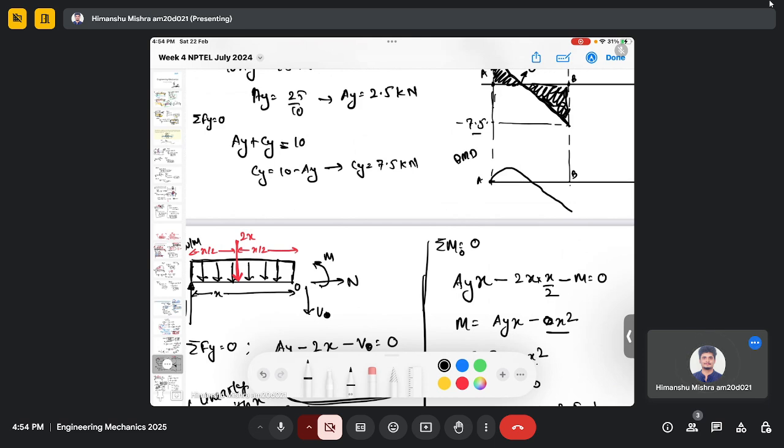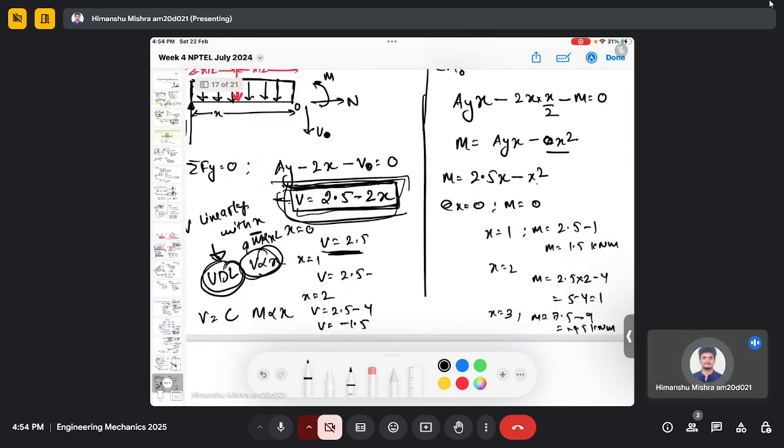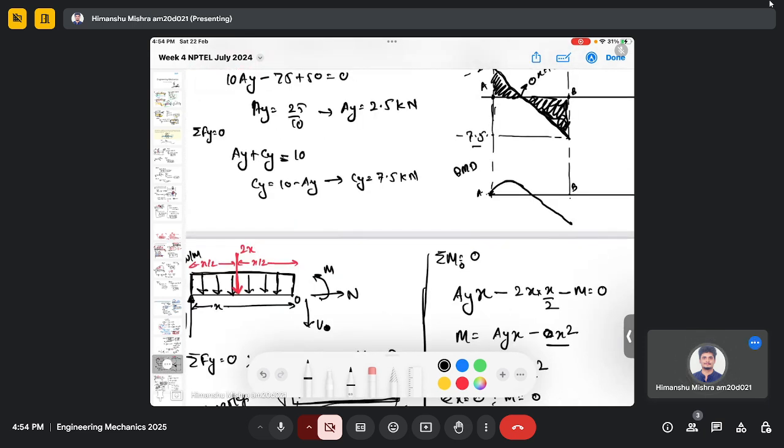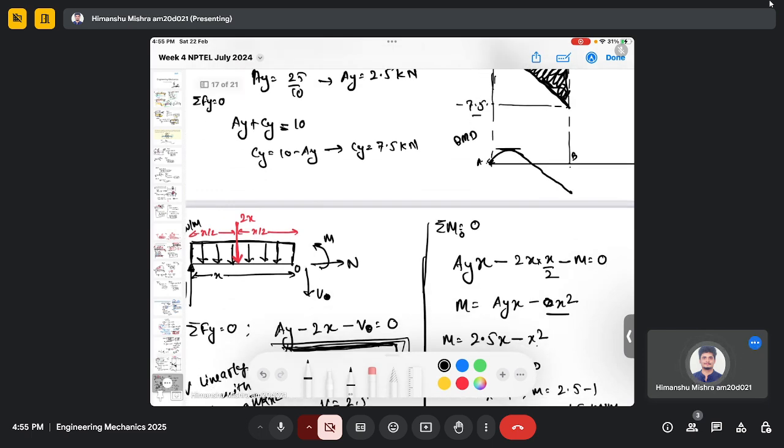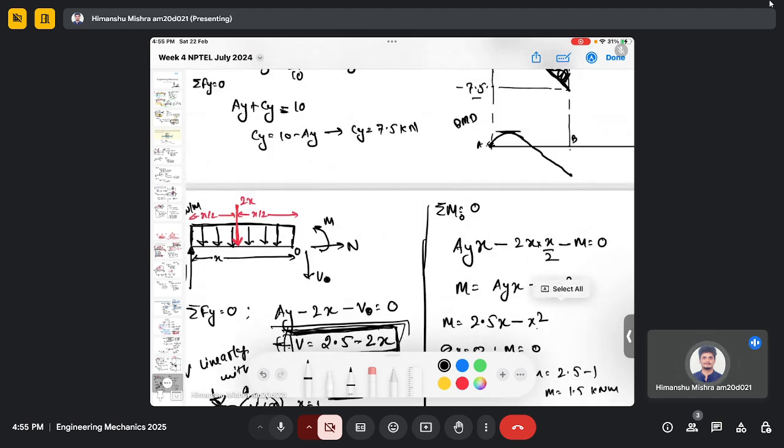Like this you will have. Now in order to find where your bending moment is maximum, you have to draw a tangent at each point on this curve, and if the tangent is 0, you are at the maxima of this curve. At the maxima, the slope of this curve will be 0, and that maxima will be the maximum BMD. So I'm just using the concept of calculus here, trying to find the maxima of this curve.